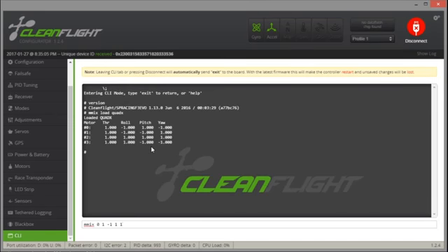And the way we change them is we want to change the yaw to be backwards of what we got right now. So we want negative to be positive and positive to be negative in the yaw column. The rest will be the same. Throttle is always 1, so you can just remember that. To do that, we pick a row we want to change. So in this case, we're going to do row 0. So we put a 0 in, and then we copy all 3 of the rest of them in that row except the yaw. We want to negate that to a 1.